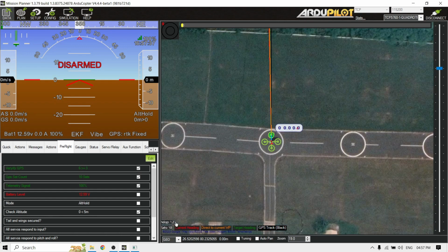That's pretty good. But as HDOP starts increasing, we need to start worrying about the GPS accuracy. It might glitch, or the accuracy might be very poor. That might create a lot of issues that we need to consider here.